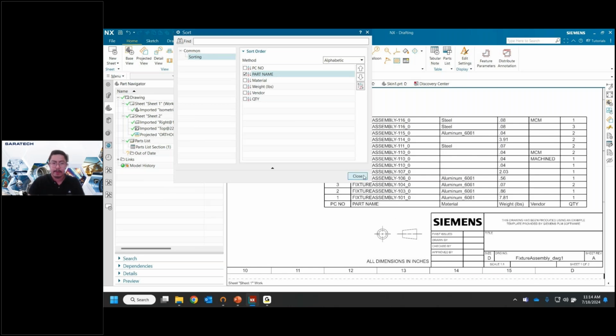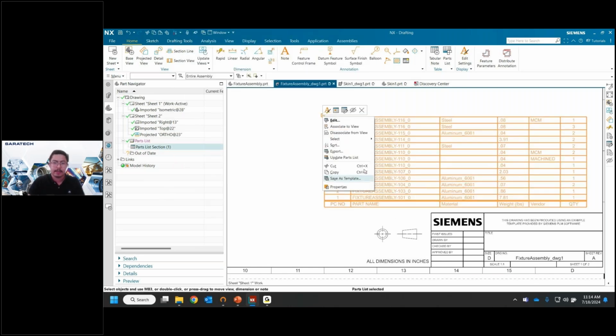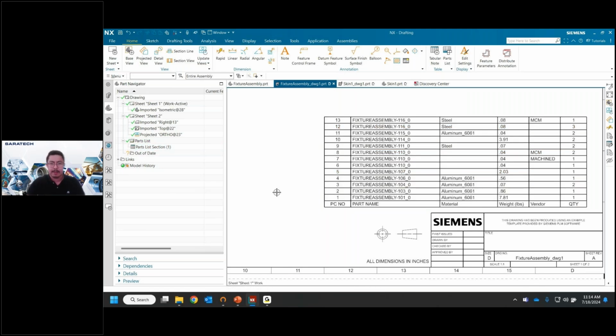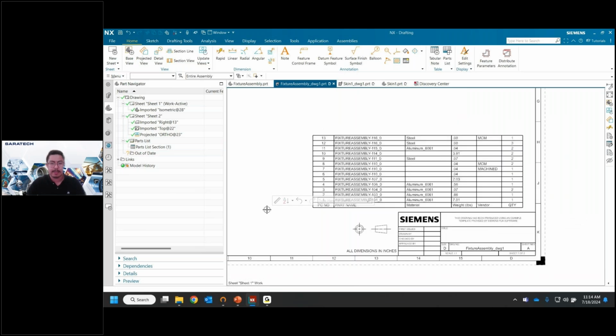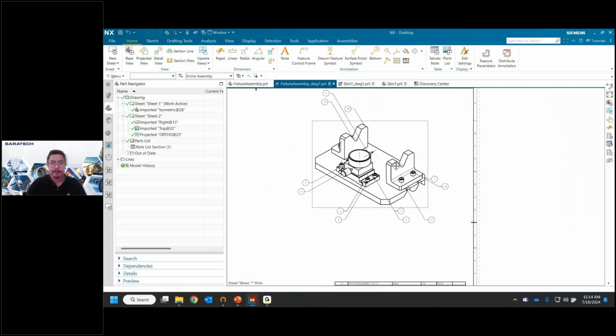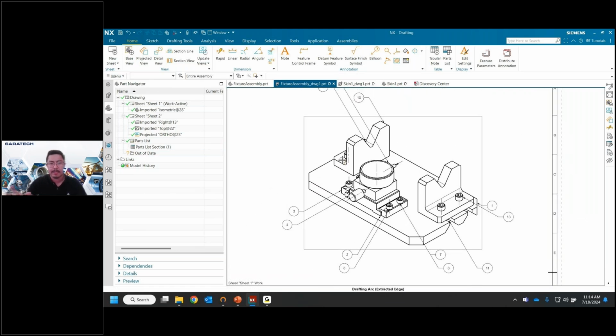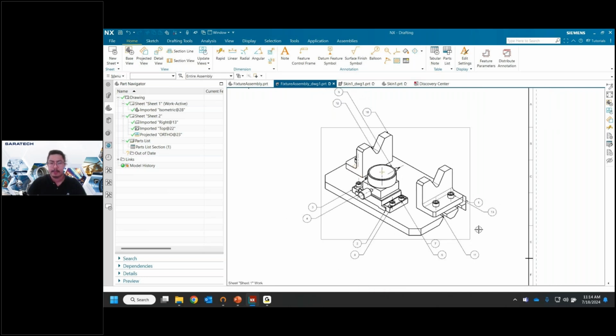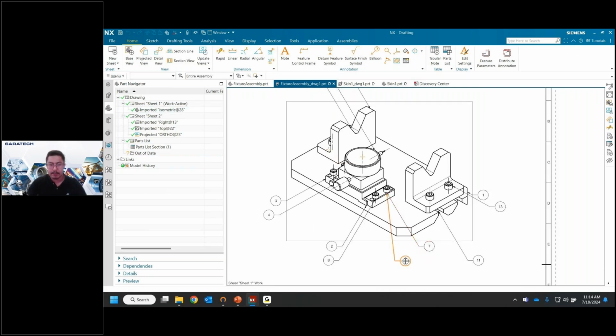And then once you have all this set up, you can go ahead and right click and save this as a template. Right, so now not only can you use this for future uses, you can upload it to maybe a site folder and have people pull that. So you're making your life easier and other people's life easier. So this is a great handy tool. Right, you can see those balloons were populated in my ISO view. That's very easy. Looks pretty good in terms of organization here.